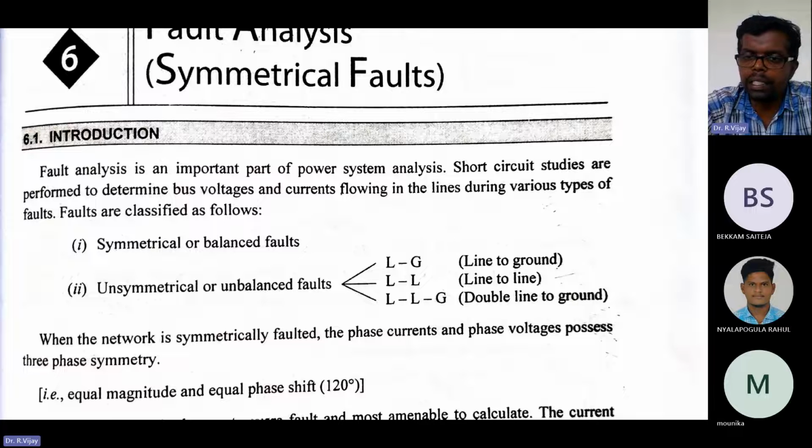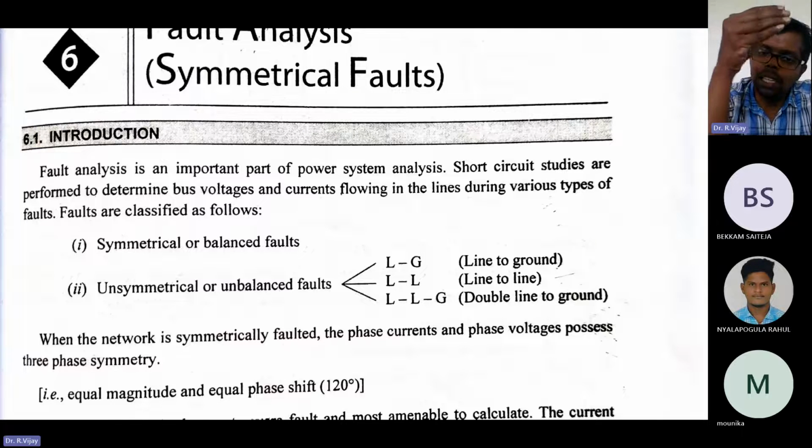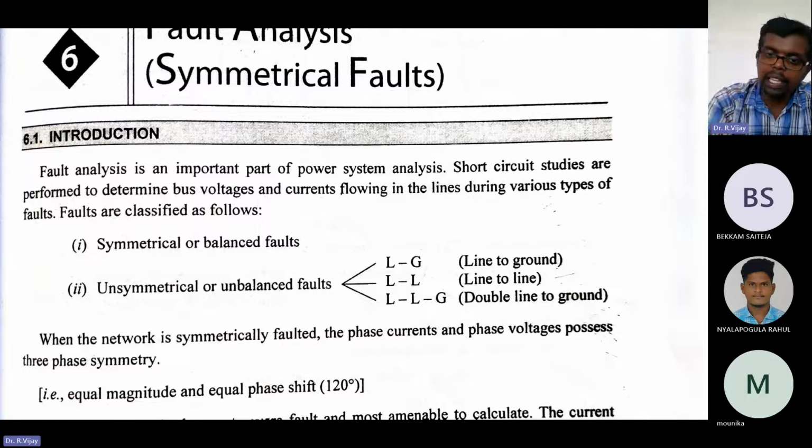Sometimes if it is raining heavily, and on the poles themselves you may see some plants, some shrubs. They may go up to the line and touch it, and that green shrub will easily conduct. So it may go to three lines, a triple line fault. That may also happen with some snakes, some birds, some monkeys, which may conduct across the lines.